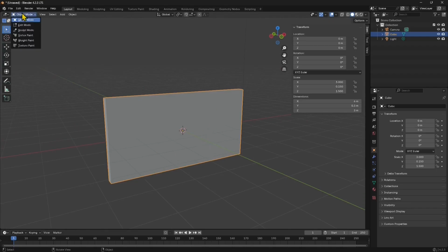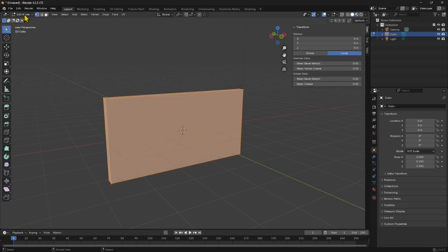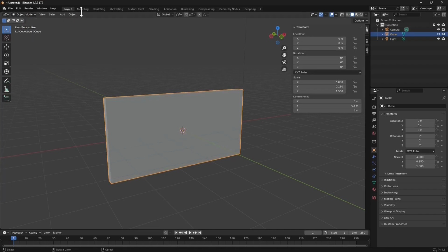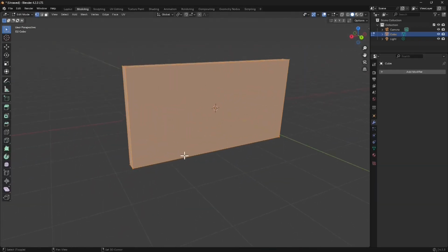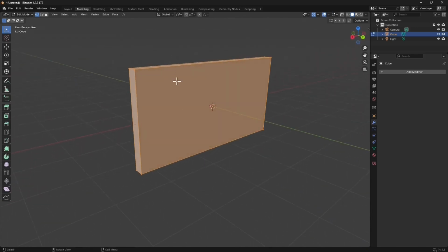Now I can cut through using the Boolean, but instead I want to use polygonal modeling, or hard polygonal modeling. So I need to switch from object mode to edit mode. I can go in the modeling interface directly, and I am already here in editable mode. So I can edit this box using the vertices, using the faces, using the edges. And if you find this difficult, you can check the Blender video course in the channel, and we also have other courses and guides.